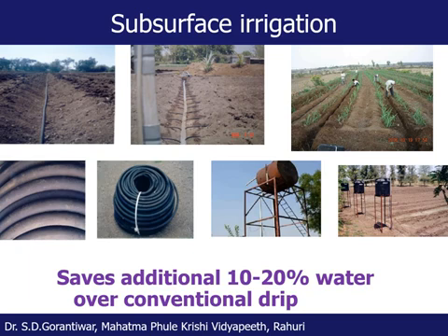The porous pipes are installed actually. Remember that these are not inline drip or subsurface drip, but porous pipes. These porous pipes are installed as I have shown you in the second figure, and how a porous pipe looks, I have also shown in the bottom photographs. They are installed just like we install drip laterals into the field. These porous pipes are connected to the sub-main pipeline, the sub-main is connected to the main, and the main is connected to the overhead water tank in this case. Remember that this is the overhead water tank.